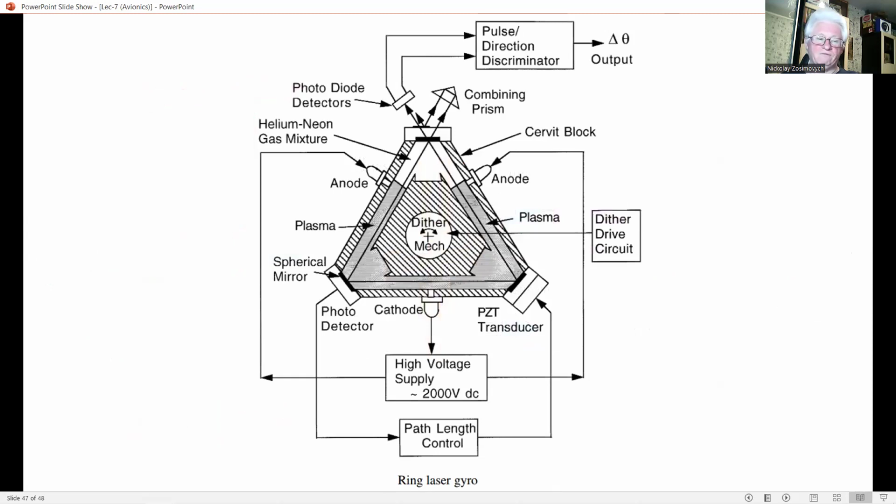The pair of tuning forks and their support flexures and frames are batch fabricated from wafers of single crystal piezoelectric quartz and are micro-machined using photolithographic processes similar to those used to produce millions of digital quartz wristwatches each year. And this slide shows a fabrication wafer.